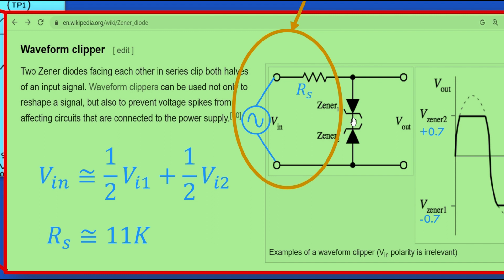It generally blocks current in the other direction, so this second one at the bottom here would block current from coming down. And so there would be no current flowing through this leg and whatever Vn is would go on to the rest of the circuitry. However, all diodes, when they're blocking stuff, have a limit as to how much voltage they can withstand. And if the voltage gets bigger than that, then current will start to flow. In fact, it will flow a lot.